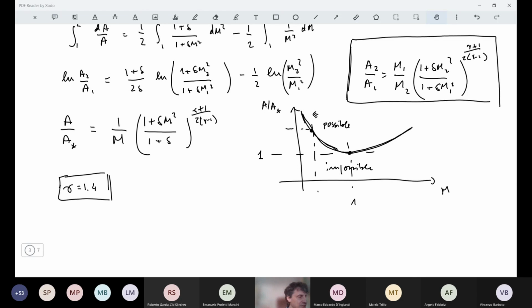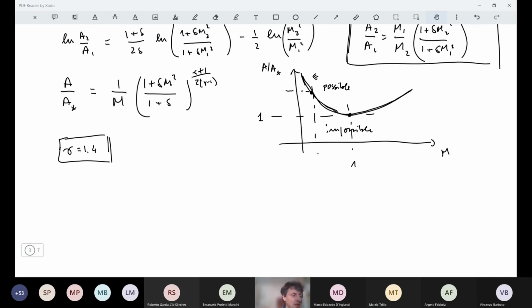the kind of propellants I'm considering, and also the temperature in principle. The other warning is that we are now always talking about calorically perfect gases, which is not the case typically in rocket engines. So be careful in using tables about this law. Often tables are obtained with a given value of gamma. So if the value of gamma is not available in that table, you cannot exploit tables for the computation.